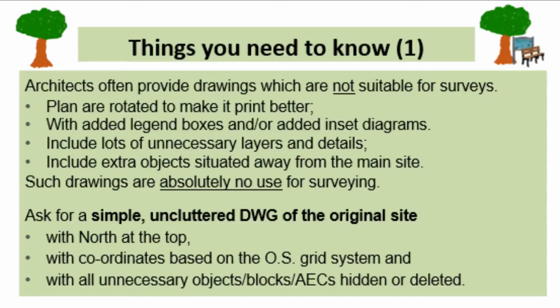Architects often provide drawings which are not really suitable for surveys. The plan has been rotated, often to make it print better. They've added legend boxes or detailed inset diagrams. There's a lot of unnecessary layers and details, or they've included objects situated well away from the main site. Such drawings are absolutely no use for surveying.